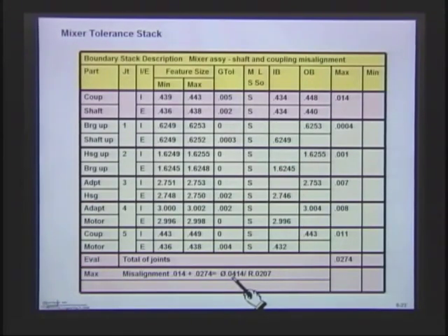So it looks like we're a little bit over. We're about, what, 1,500 or so over. So we have to go back then and reallocate our tolerances. So we had a pretty good guess initially. So that's what I would like you to do: if you're there with some manufacturing people or some quality or design, it's kind of a little bit of a design review here now. I want you to go back and take a look at where you're going to reallocate to make sure that we fell within that tolerance.